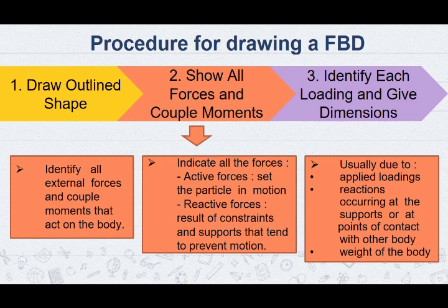The second procedure for drawing an FBD is to show all forces and couple moments. First of all, you need to identify all external forces and couple moments that act on the body. The second one, indicate all the forces. Active forces set the particle in motion.